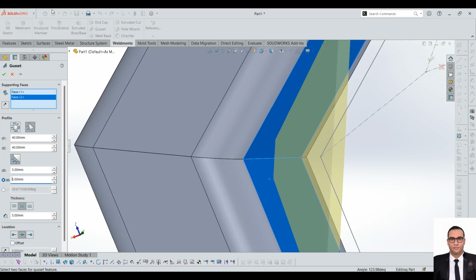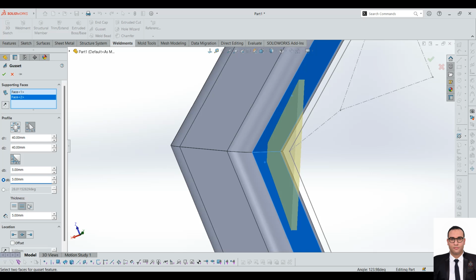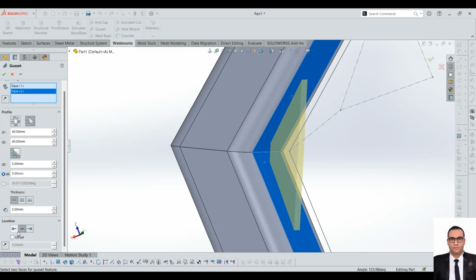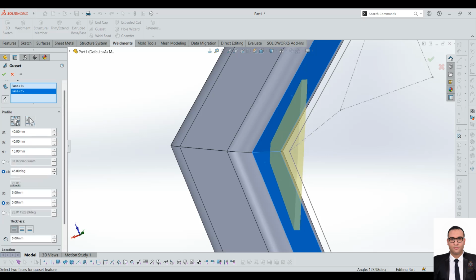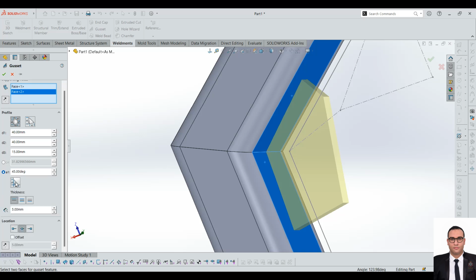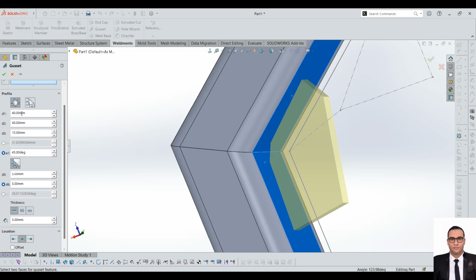It will be easy to weld here, and here we can specify the position of that gusset, and we can also give it an offset as desired. And the same for this one. We can also give it an option here, and we can also give it the relative dimension. Let's try per unit.